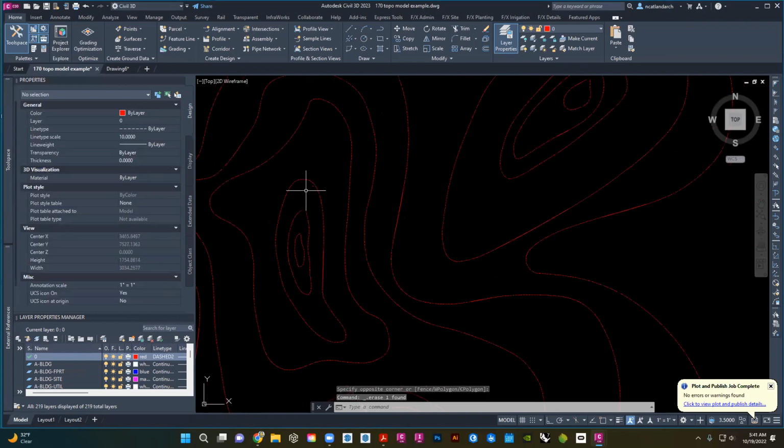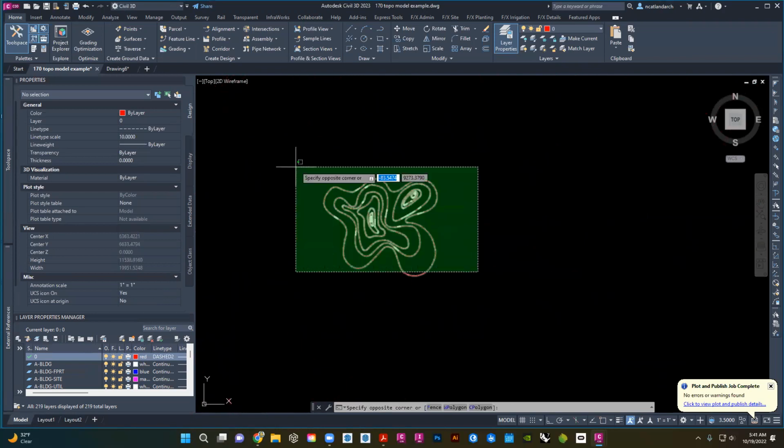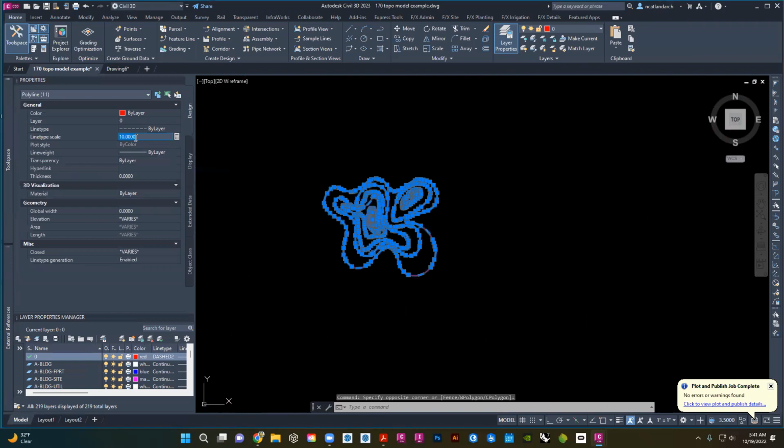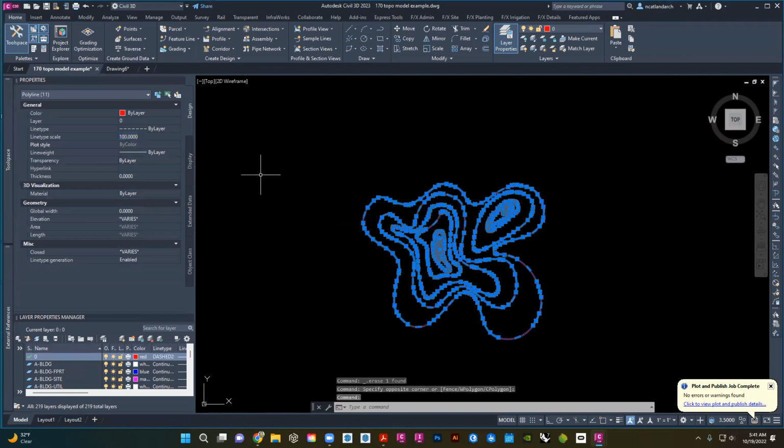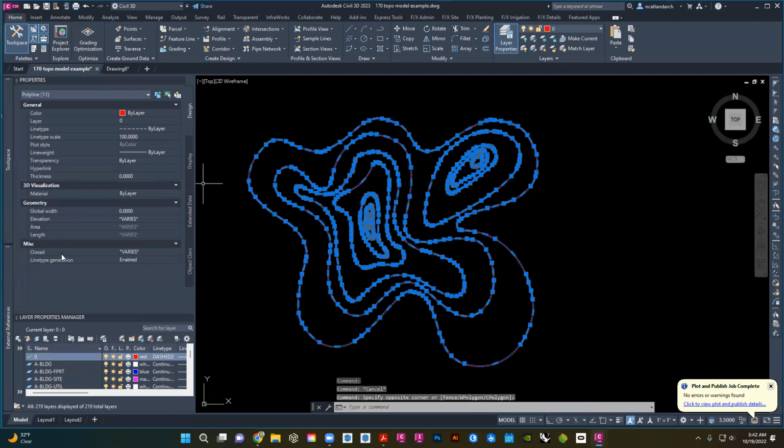You see the scale change as I scaled this thing. Now that it doesn't read the same, I want to just go through and select this now for my line type. I think I had this set to like 100 before. And yeah, also, I have my line type generation enabled. Make sure it's enabled, and it just keeps the dashes equidistant, regardless of where the grid points occur.